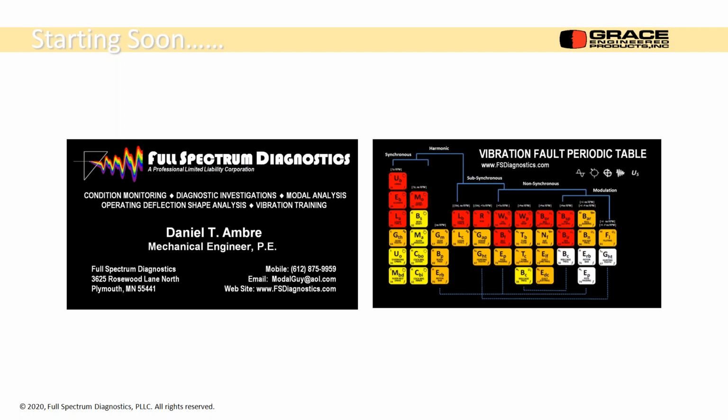How often are these online sensors needed for calibration? It depends on if you're in the calibration business, then they need it all the time, but probably not very often, probably maybe once every year or two. And you can do that if you have a portable shaker. You can buy them from IMI, PCB, two different companies, and then